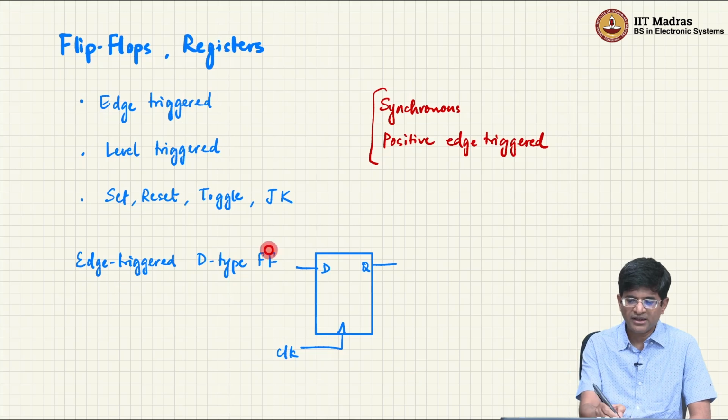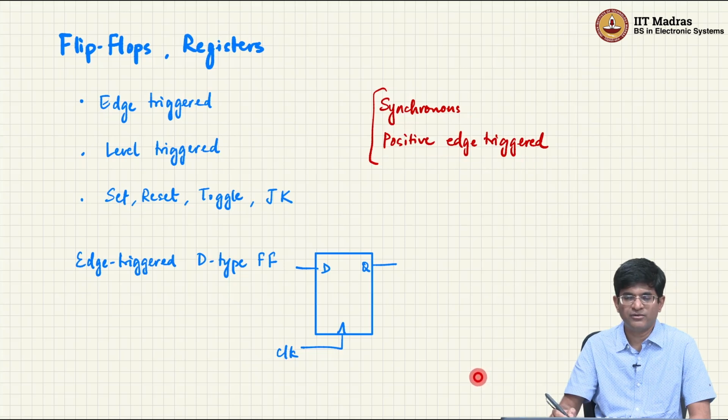And by restricting ourselves to so-called synchronous designs, where in particular we are going to be working just with positive edge triggered D-type flip-flops, right? You can actually do a significant amount of analysis on circuits, right? And even prove certain properties such as how they will evolve with time. Okay. Now, this is not the only kind of digital circuit. There do exist circuits where we can even use asynchronous logic, you can use latch based design, you can use other kinds of flip-flops than D-type flip-flops.